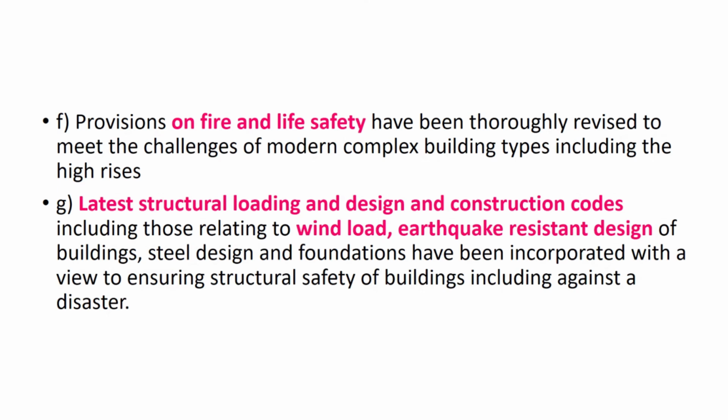Okay, so we are talking about this. Here what they have done, again they have compromised on the structural integrity of the beams itself. Some more photographs. Now here the entire depth of the beam is gone, taken the entire pipe through that, and he is doing his job. Please pay attention. Many times we tend to ignore all these things.